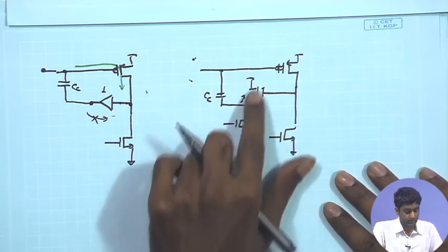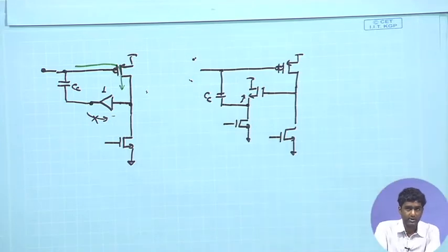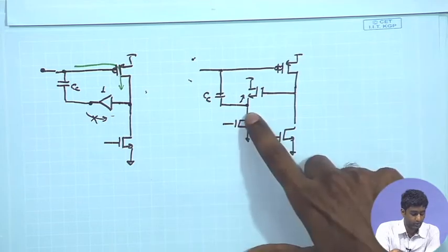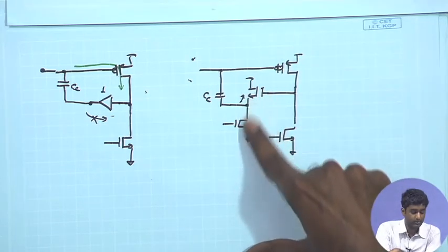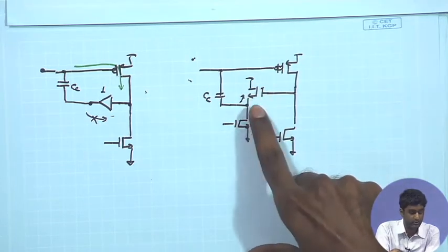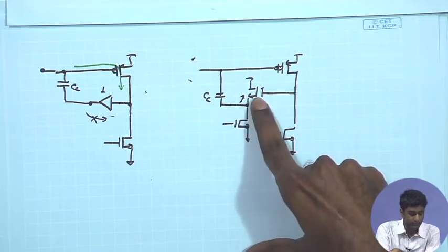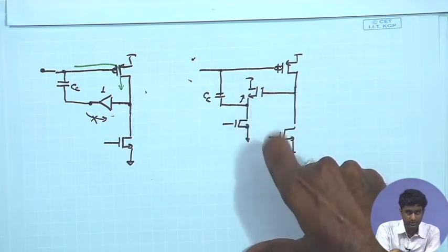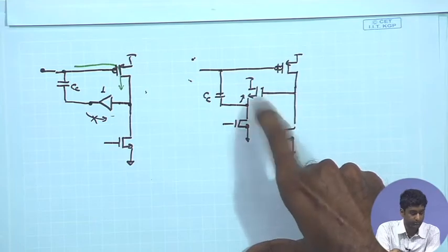But once again, when we are trying to incorporate this stage and trying to make the output impedance lower, it is going to add additional power consumption in this particular branch, because it will need sufficient bias current to have a large GM, so that the output impedance of this stage is sufficiently low and it is acting like a good common drain buffer.